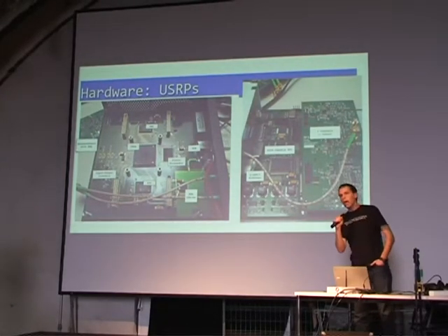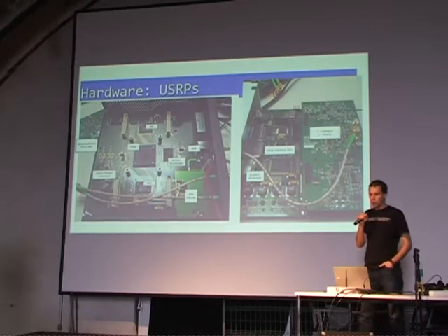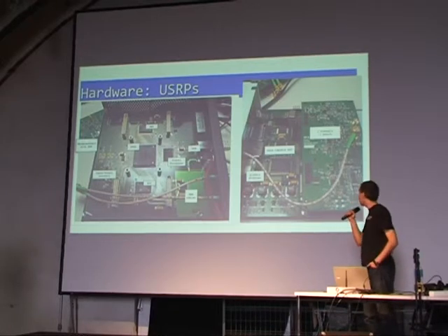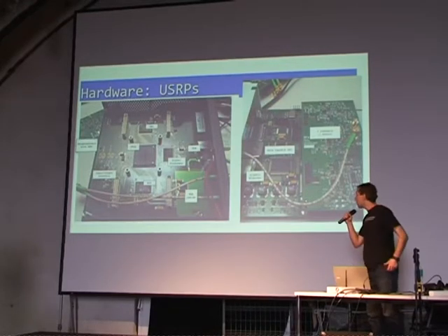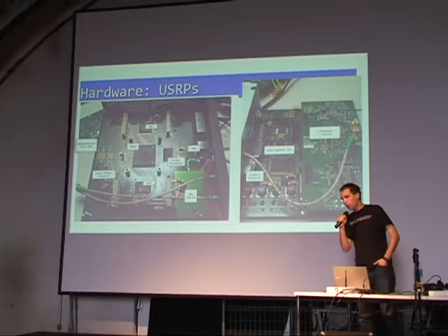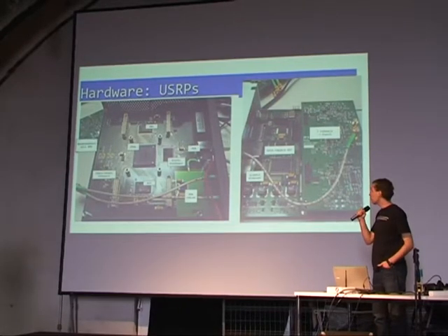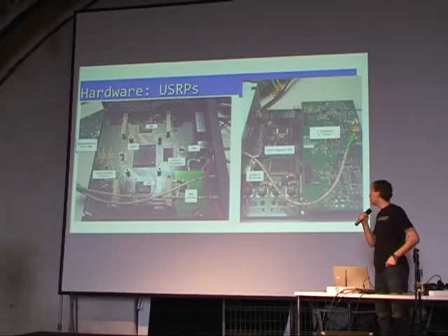Trying to at least schematically explain what kind of hardware is working here. At the USRP, you have a set of ports. You see two ports for the USRP2 above and 2 ports down. So in short, it has 4 ports. And you can have 2 different daughter boards because it has full duplex USB 2. And the daughter board is shown in the background for the black one, which is the USRP1.